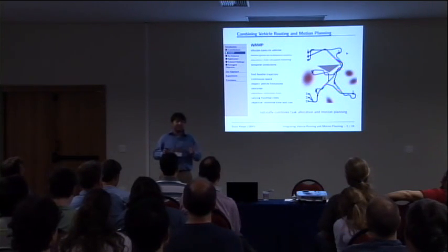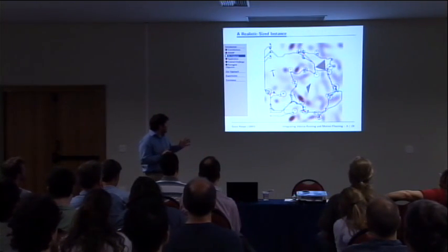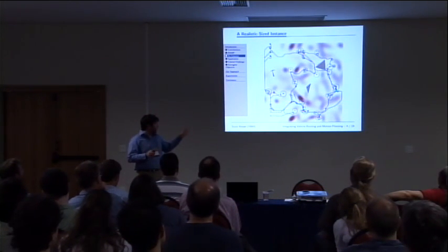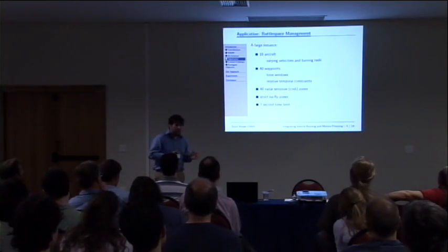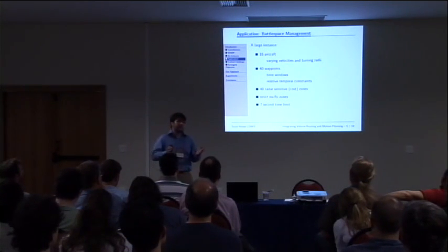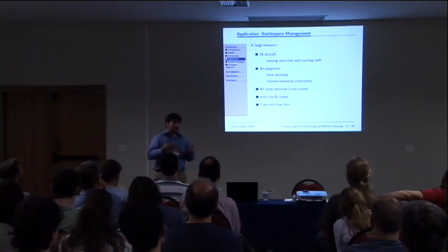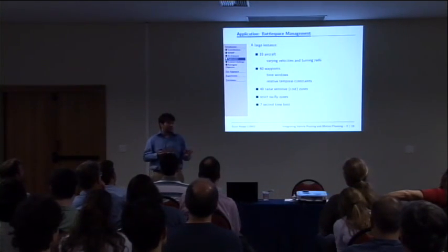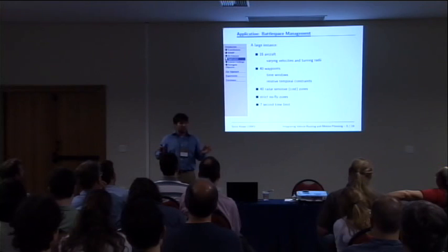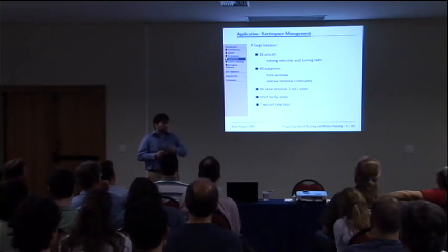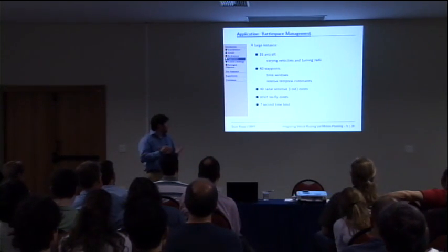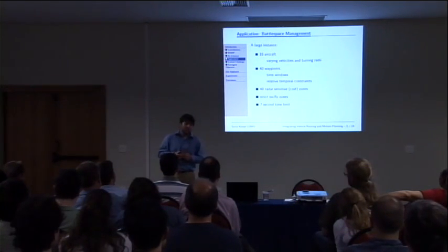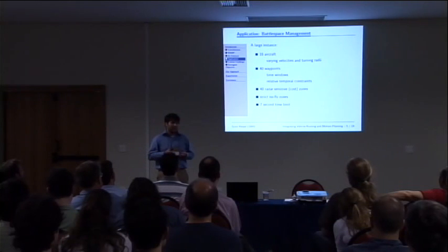So a more realistic sized instance is this one. We're looking at more waypoints, larger spaces in general, larger fleets. Description of these larger instances: we're looking to scale up to 16 aircraft with varying velocities and turning radius. So these are unique vehicles, not necessarily uniform across the fleet. We scale to 40 waypoints. Each of these waypoints has time windows, relative temporal constraints, as well as configuration constraints at that waypoint.